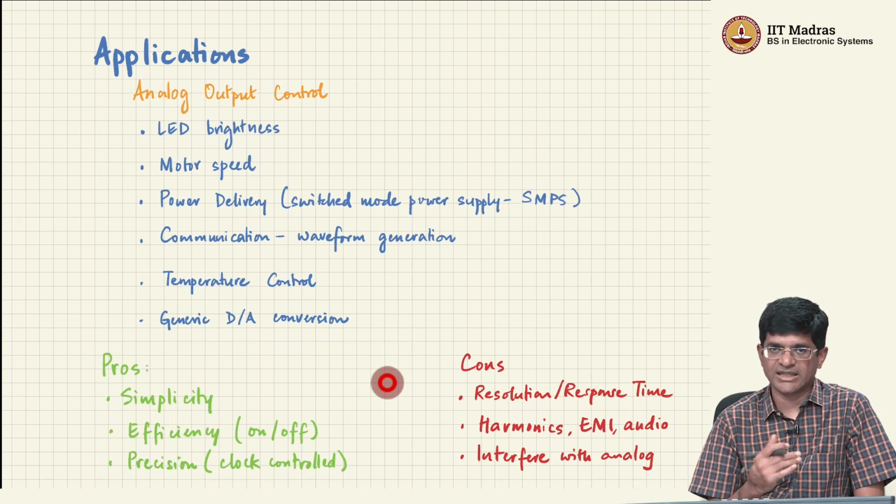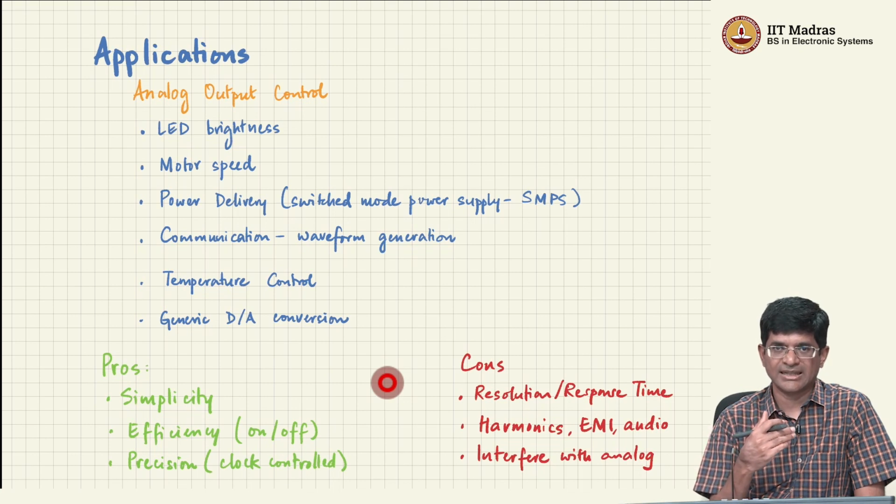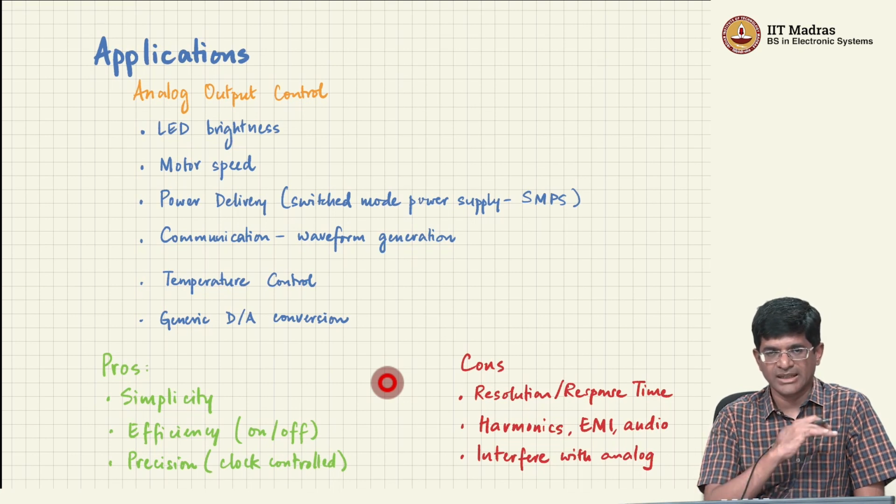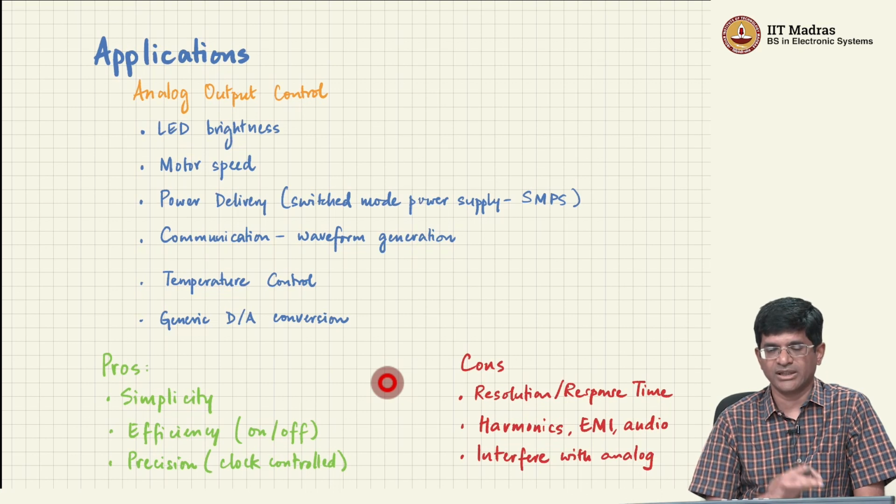The LED itself is not glowing at half brightness or 1/3 brightness. It is either on or off. But because your eye cannot see things that are varying at 1 kilohertz, it automatically does an averaging and tells you that, hey, this looks like an LED at 1/3 brightness.